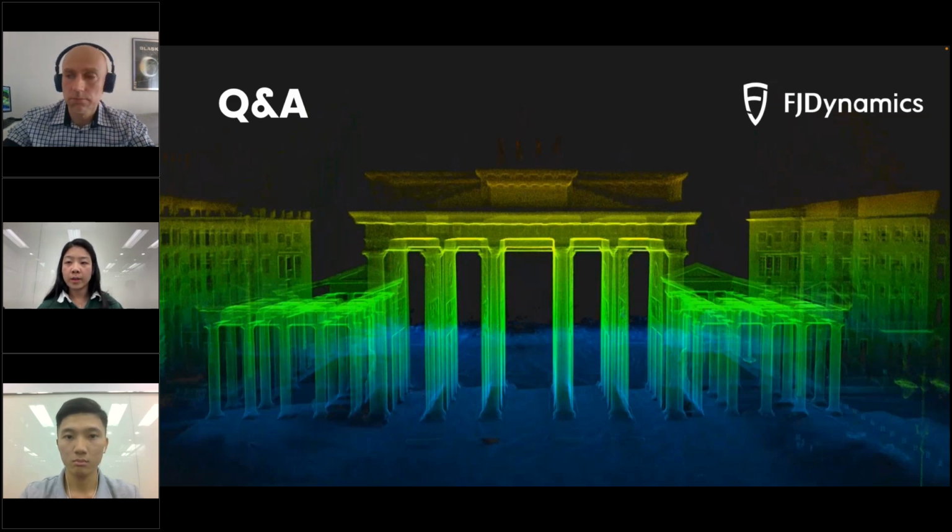Great, thank you. And then some clarification on the previous question. Some of the loops coming in from the scanner have problems with horizontal or vertical skewing, I guess, meaning that my ground is not level or my walls are not vertical. I think this comes down to a couple of different best practices. First, when you initialize the scanner, you let the IMU register correctly. So it's better to have it on a flat surface when you initialize. And then when you scan, obviously try to keep it still, not shake it too much or suddenly move it around or wave it around. Jacob or Dennis, do you have any experience with this problem and any suggestions on how to avoid it?